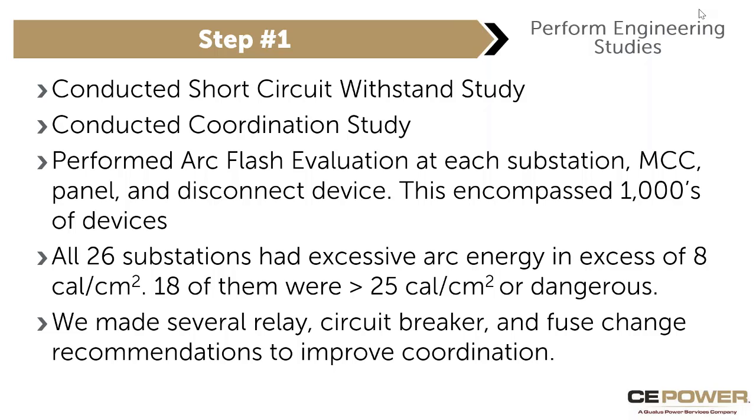As far as first phase, typically when we're done with that, we'll pluck off some of the easy things where you change potentially some relay settings, maybe change some fuses on a short outage. Replace some circuit breakers or some fuses that are over dutied. Really go for that low hanging fruit first to improve what you can and see where you're left.